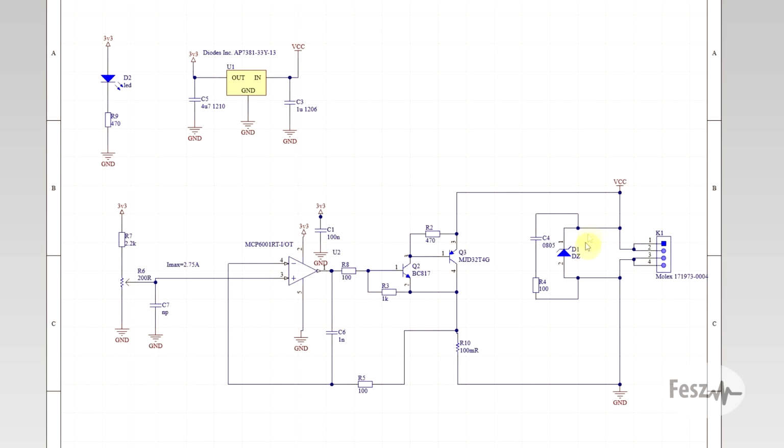And the second thing to mention is a Zener diode, which serves two purposes. On the one hand, if you're incorrectly supplying the circuit with too large of a voltage, larger than the diode rating, then the diode will start conducting and protect the circuit from exposure to overvoltages. And second, if a reverse voltage is applied, again the diode will conduct, preventing a reverse voltage destroying the circuit. Now, adding in a fuse, maybe even a polyfuse, would have been quite helpful here. But even so, these two elements should protect the circuit from most of the cases of mishandling.